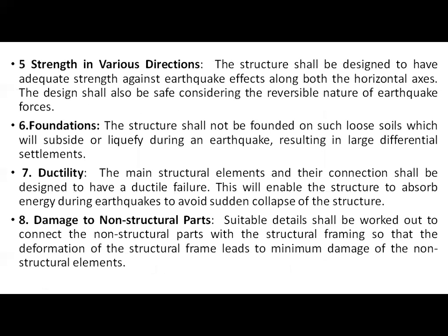Completed. Next point is the strength in various directions. Next one is the foundation. Next one is ductility, and last one is the damage to non-structural parts. So strength in various directions. The structure shall be designed to have adequate strength against the earthquake effects along both horizontal axes. The design shall also be safe considering the reversible nature of the earthquake forces.